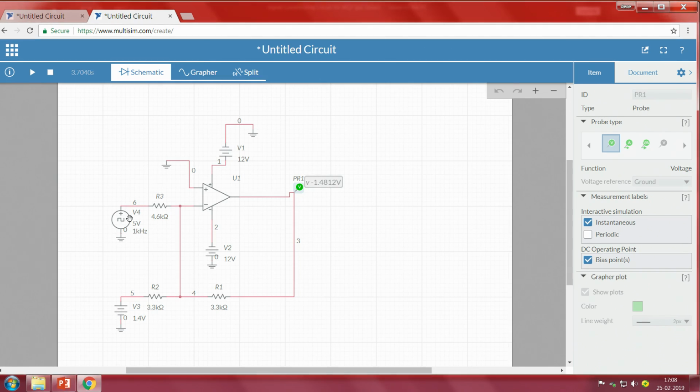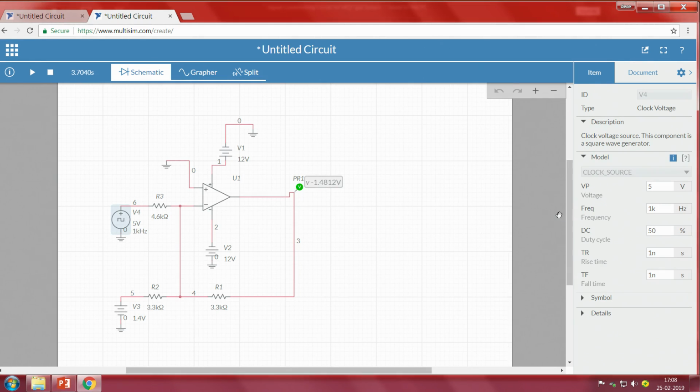And then here again, ideally, you can adjust the duty cycle. So I am adjusting this to 40% because based on our gas sensor specification, which said 60 and 90, you calculate your duty cycle. The on and off period is very specific to the type of sensor you are working with. And it can only give you the higher voltage, that is the upper voltage. Your source cannot give a different level in voltage, that is either 0 to 5 volts.